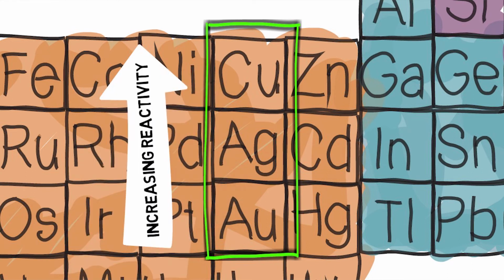So you've definitely got gold, which is a very noble metal that will typically be very hard to react. And silver's a bit easier, and then copper's much easier. And this can impact our recovery and make the process unprofitable. So say if we had ore and it had a lot of copper in it, what would happen is that would consume all our cyanide, and we'd have to add a lot more to eventually get the gold out.